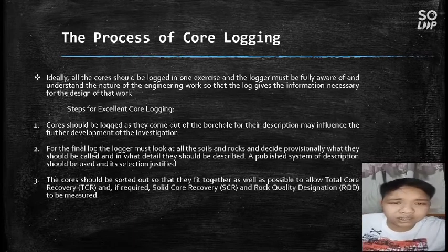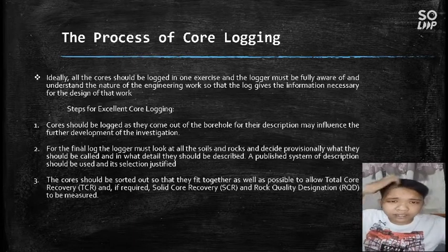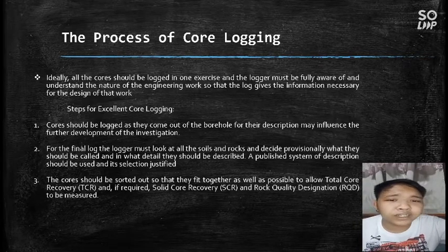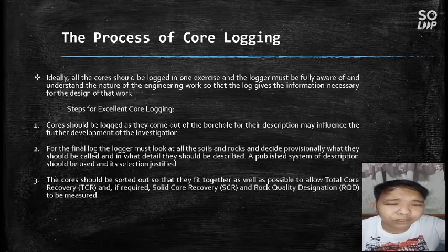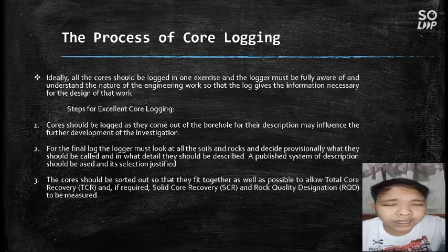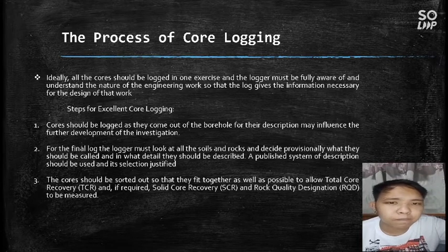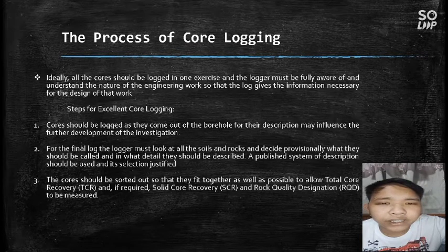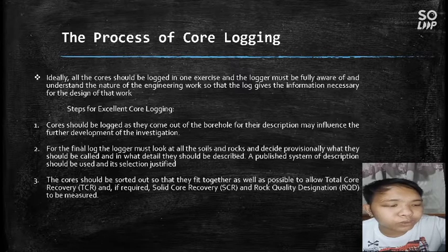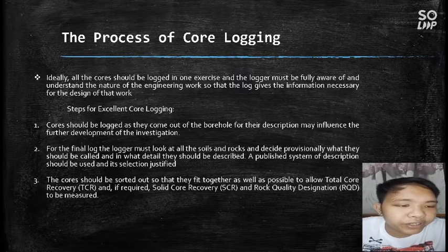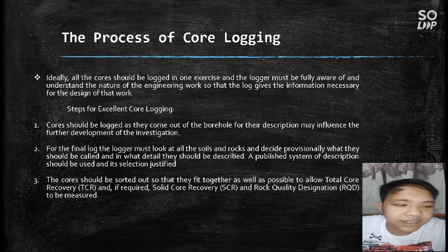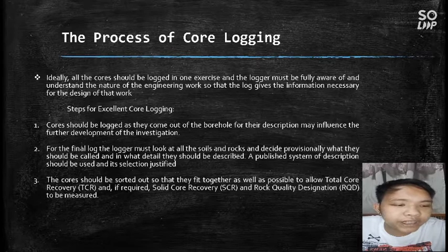So obviously, the final log should be based on the characteristics of the soils and rocks that the cores are drilled from. Lastly, the cores should be sorted out so that they fit together as well as possible to allow total core recovery, and if required, solid core recovery and rock quality designation.